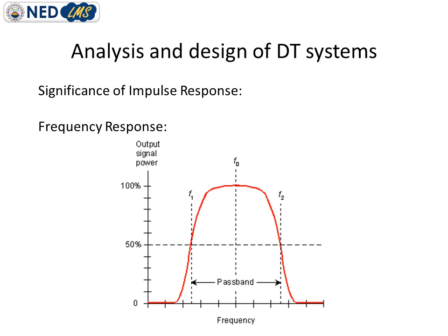So we can say that this frequency response is actually the response of a band pass filter, which means if I apply very low frequencies, this system will not provide significant gain to those frequencies, and the same will be true for very high frequencies. If I apply very high frequencies to this system, it will provide insignificant gain to those frequencies.